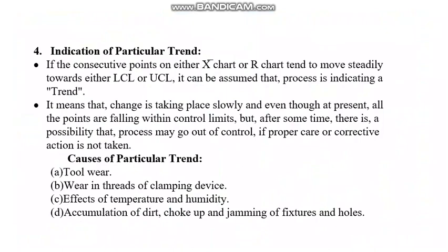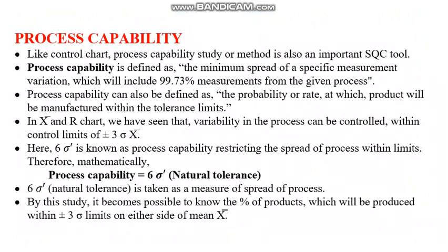Why is it taking place? It could be because of tool wear, or wear in threads of clamping devices, or the effect of temperature or humidity, or the accumulation of dirt, choke up, jamming of fixtures, holes, etc. These can be the different causes for the trend that we are seeing.